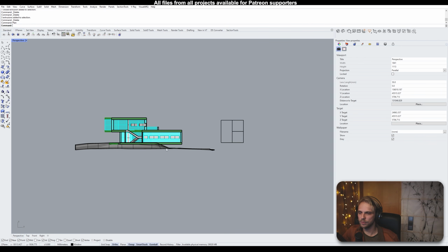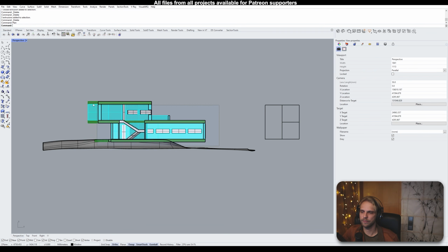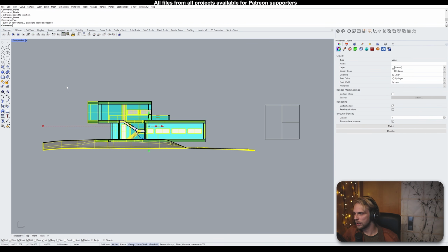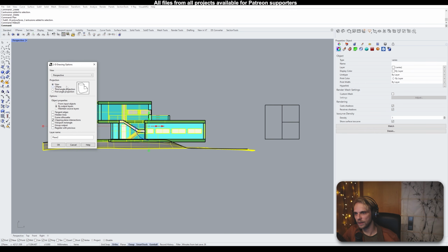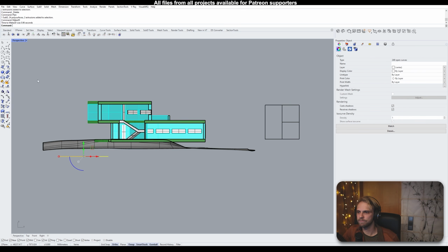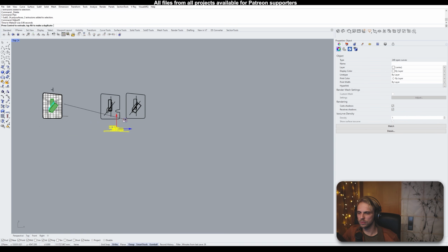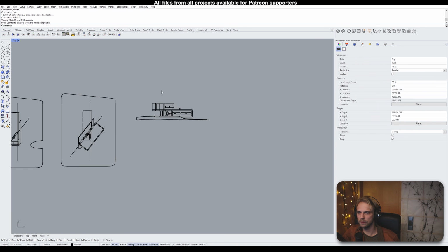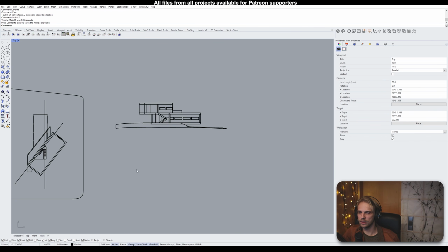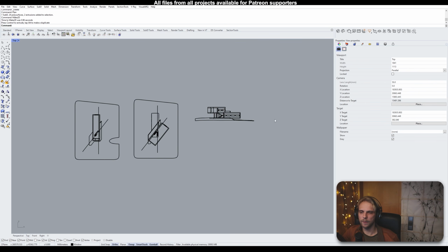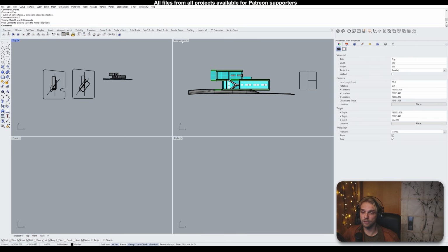You have your plan view, you select your objects, you type in make 2D. We call this section 1 or section AA. Hit OK. It generates the section. We drag it out to wherever you want it to be. Let's say here. There's our section. We'll clean it up, and that's it. Now you have your section done.